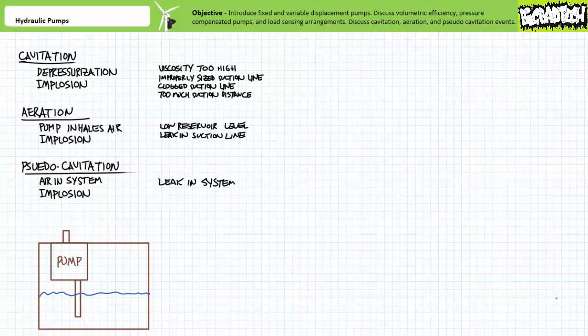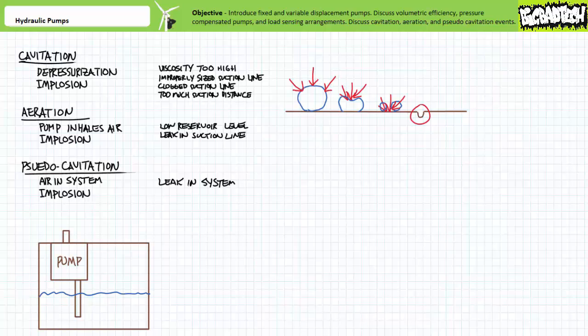Cavitation is an event characterized by a liquid undergoing a rapid depressurization event and a subsequent rapid repressurization. When liquid is rapidly depressurized, it can enter the vapor phase. Think of water exhausted into the vacuum of space. It boils away since there is no pressure to hold it in the liquid phase. Additionally, when rapidly depressurized, any gas dissolved in the liquid can come out of solution and form bubbles. When the liquid in vapor phase is rapidly repressurized, the bubbles rapidly collapse, forming shock waves, noise, high temperatures, and high-pressure jets of fluid that can pit and abrade metal surfaces.